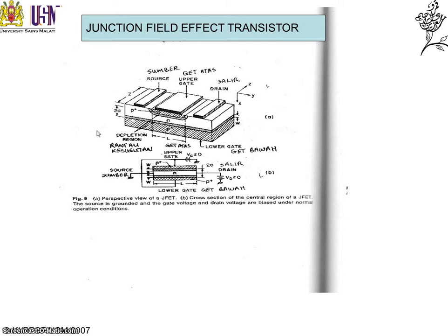If we look at the JFET that we have here, basically we have a source, gate, and drain. You are controlling everything with the gate, so it's a three-terminal device: source, gate, and drain. The important feature is that current through the two terminals, the source and the drain, is controlled by small changes in the current or voltage at the third terminal, which is the gate.